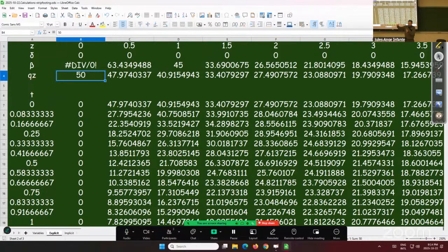So over time, you cut in clay, you have a nice vertical wall, and over time it starts sagging and eventually it fails. Okay, so even if your retaining wall should not take into account the undrained shear strength of clay, right? You should consider.